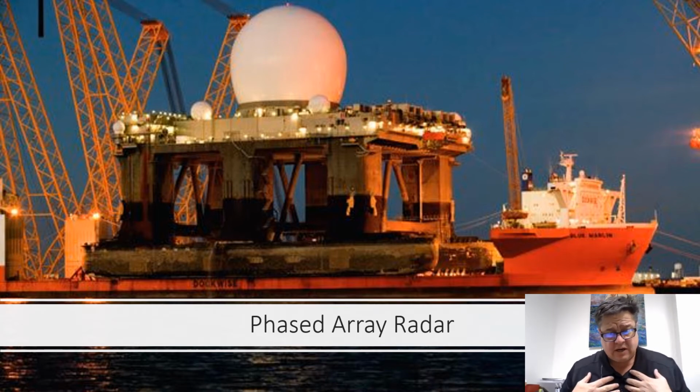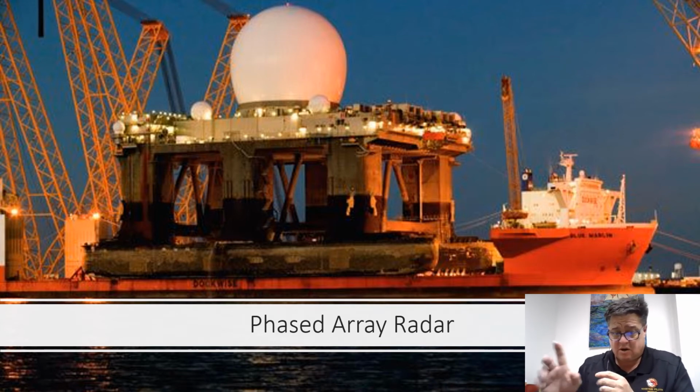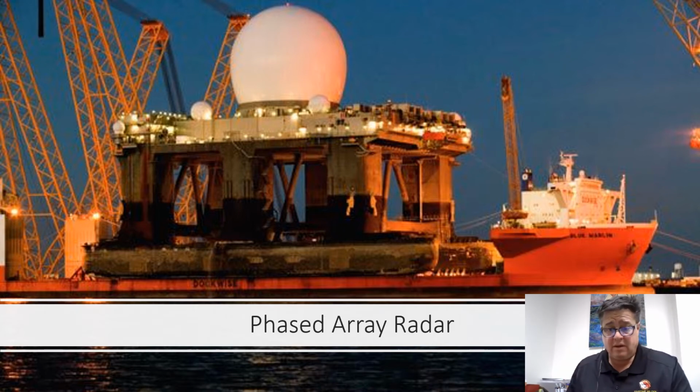We use pulse all the time, right? So our pulses go out on a single beam, goes by a degree of bearing, and shoots a bunch of pulses out, and they hit a target, and they come back in echo. And then we know that that packet of energy traveled at the speed of light, 300,000 kilometers per second. So if we know it's traveling that fast, we can find out what the echo time is. We take the time, take the speed, create a distance. That's how we establish the distance of our echo.